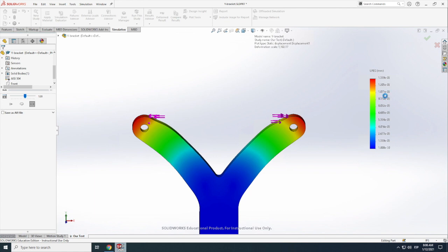Please feel free to look them up, because I want to go into the interesting stuff as soon as this stops loading, which is the topology optimization. We know from the previous diagram that there were a lot of blue areas that had very low stress, which means that we could probably eliminate them. They are not necessary in our design. So we will let Solidworks actually determine how to do that. So let's give it a moment.